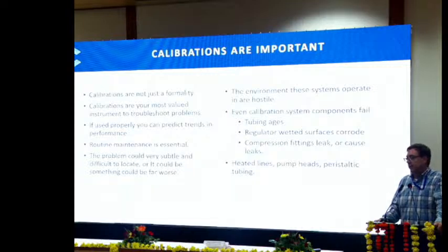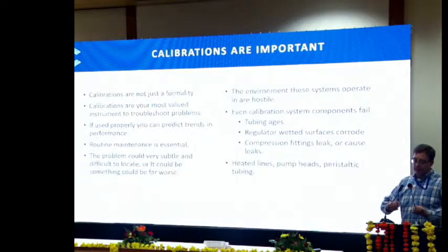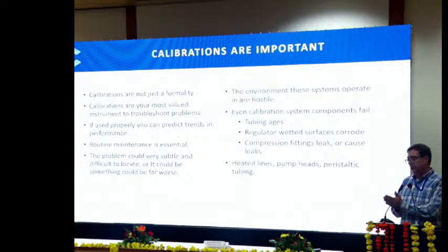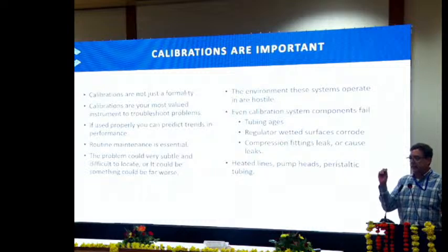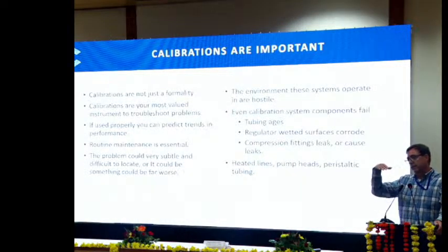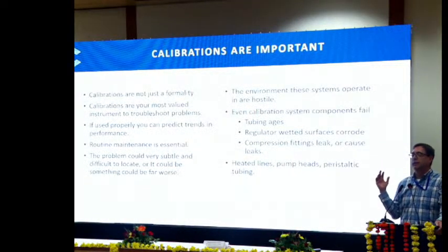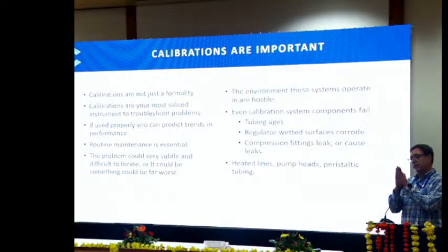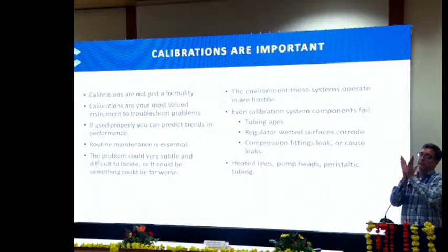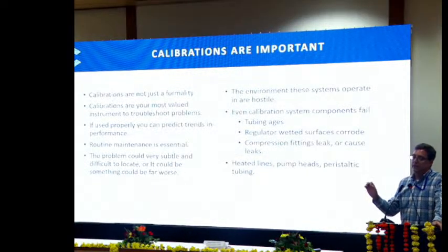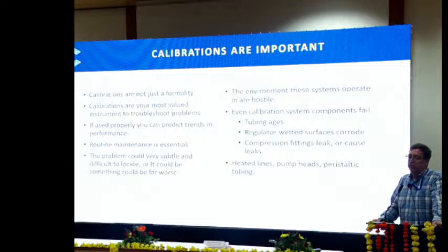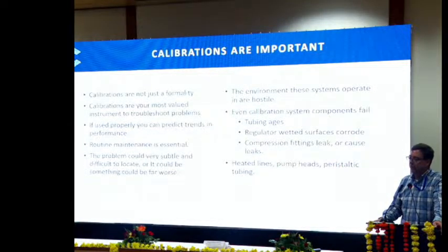Compression fittings leak. Every time you take one off and you tighten it back up, if you tighten it a little bit too much, those ferrules bite into the Teflon line, for example. Over time, they will develop cracks, and if there's any sort of weight or pressure on that Teflon line, it will cause that line to eventually just split. Depending on where it is in your system, you could potentially start pushing or sucking in ambient air, or you could be pushing calibration gas out there and not getting it up to the probe the way it's meant to be.